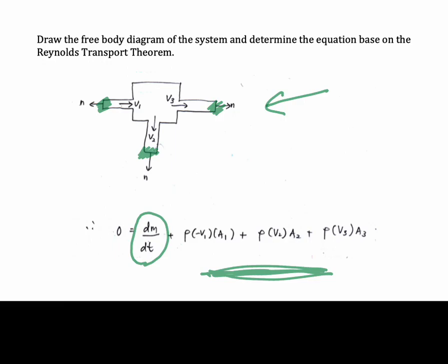So it is okay for us not to integrate that equation, because we could calculate the total mass flow rate that flows from that surface. So we just substitute the value. So we have rho Vn. The basic idea is rho Vn dA. So we substitute the rho here, and then we substitute the value of V in vector n.